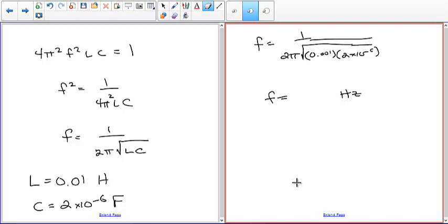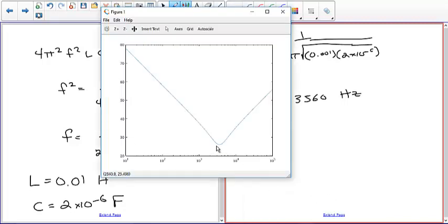and I get 3,560. So it tells me that my resonance frequency should be 3,560 based on that data, and my plot here shows that the minimum impedance is about 3,560. You can't read it to that exactness. And if you go either side of that frequency, the impedance becomes larger. Impedance is like resistance. It's going to make it so that for a given level of current, the voltage is going to be a lot lower because of that. Okay, anyway, that's...